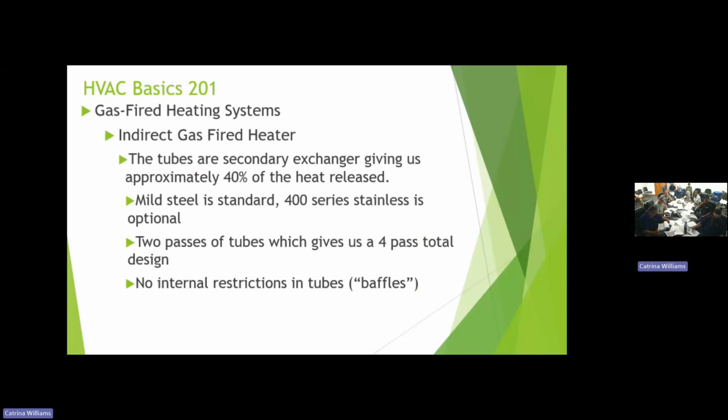And we've seen another unit, I remember, came in, they were upset with it because it wasn't working. It was a propane unit, but they had the combustion air set wrong and it sooted up. We had like 4-inch tubes. You couldn't get a pencil through there. The soot was so thick in it. A solid chunk of coal, the complete length of those tubes. Wow.